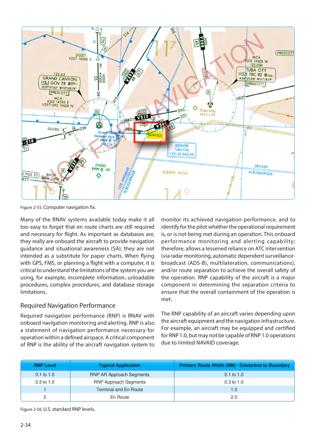Required Navigation Performance, RNP, is RNP with onboard navigation monitoring and alerting. RNP is also a statement of navigation performance necessary for operation within a defined airspace. A critical component of RNP is the ability of the aircraft navigation system to monitor its achieved navigation performance, and to identify for the pilot whether the operational requirement is, or is not being met during an operation.